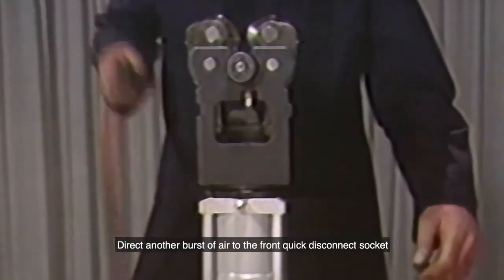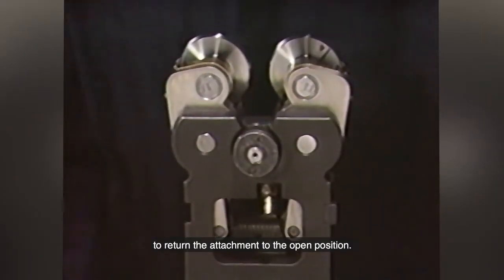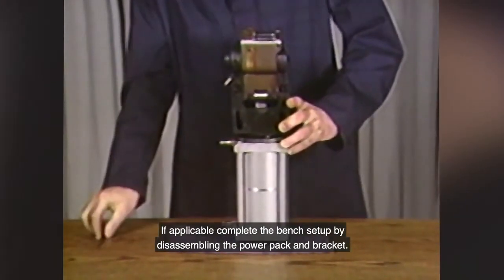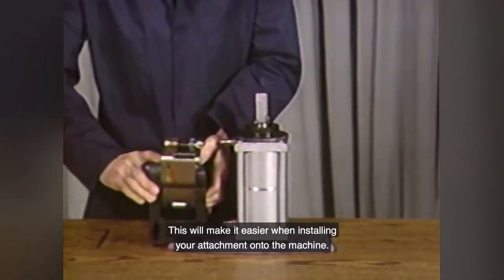Direct another burst of air to the front quick disconnect socket to return the attachment to the open position. If applicable, complete the bench setup by disassembling the power pack and bracket. This will make it easier when installing your attachment onto the machine.